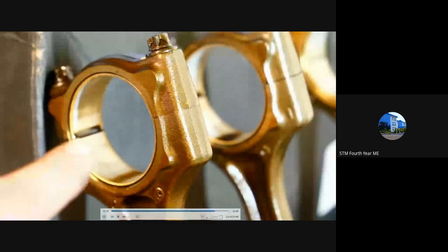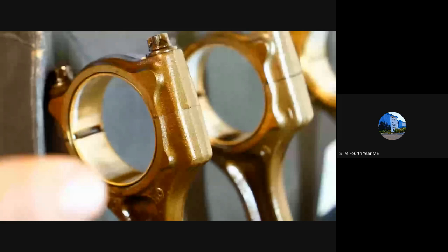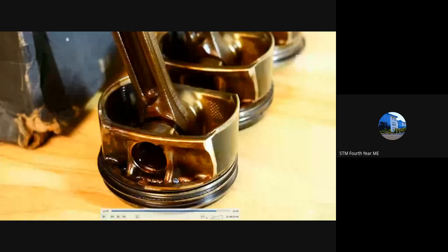So that is the bearings. So you can see the bearing inside. This is the gudgeon pin that is here. There will be a gudgeon pin that is holding the piston to the small end of the connecting rod. And you can see the oil ring and the compression rings here. This is a compression ring here, and the oil ring is exposed here a little. So that is the two oil rings and one center ring for scraping out the oil.